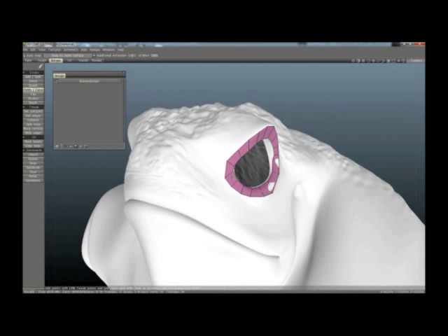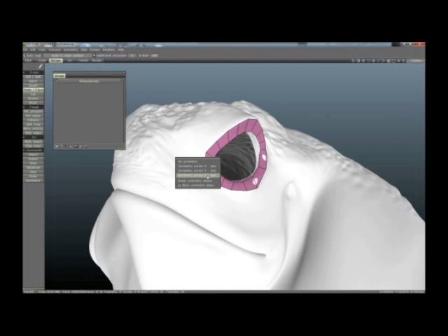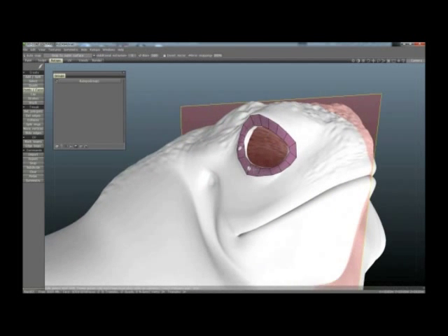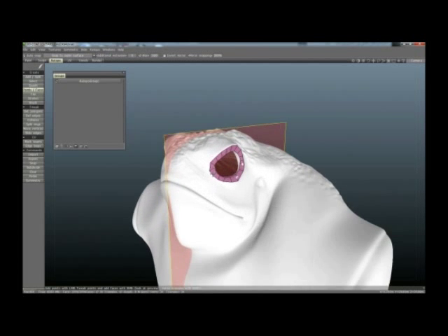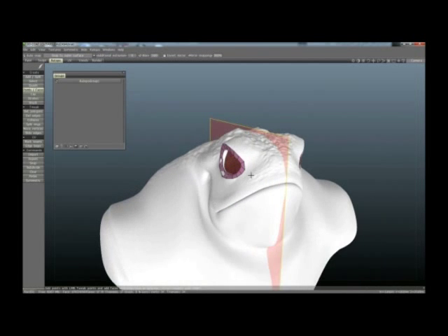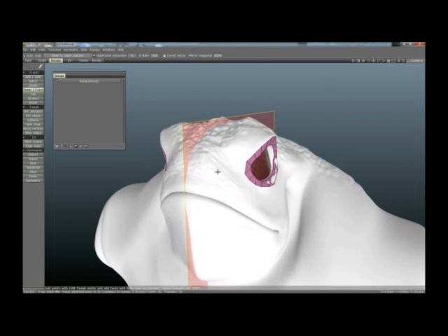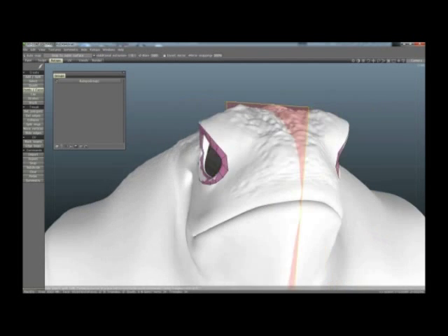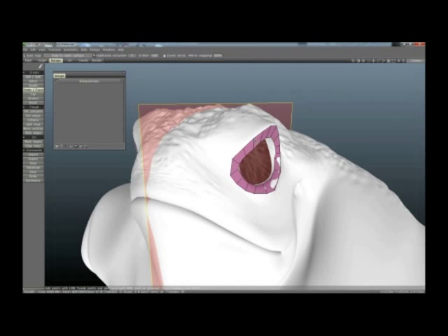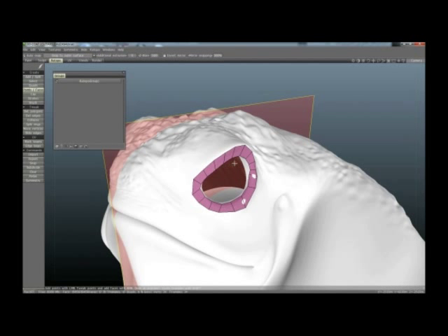To do this, we're going to hold down S, and you'll get this option up, and put on mirroring on the x-axis. Once that's done, you should get a panel like this. That's just showing you what axis is mirroring on, which is what we want for this model. If it's laying a different way or in a different direction, you may want a different axis, but that's what we want. Also, to get rid of this panel, just once again hold down S and remove the panel.